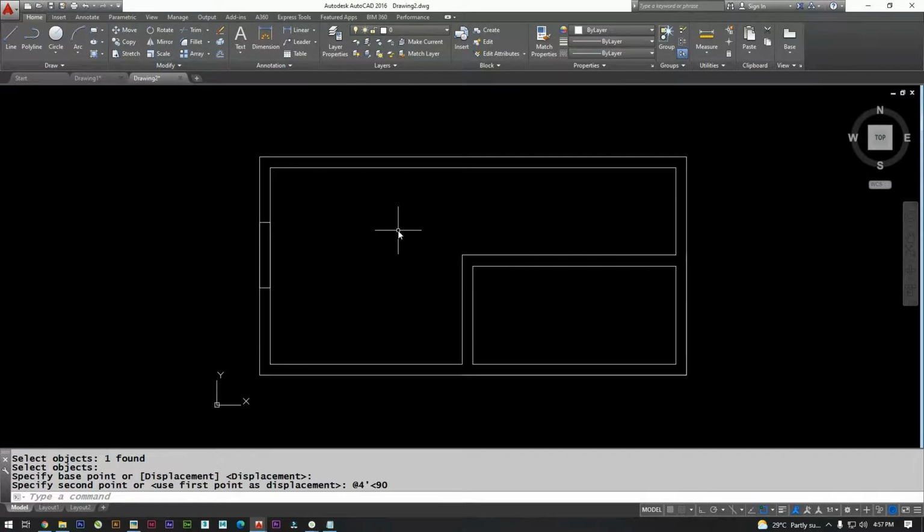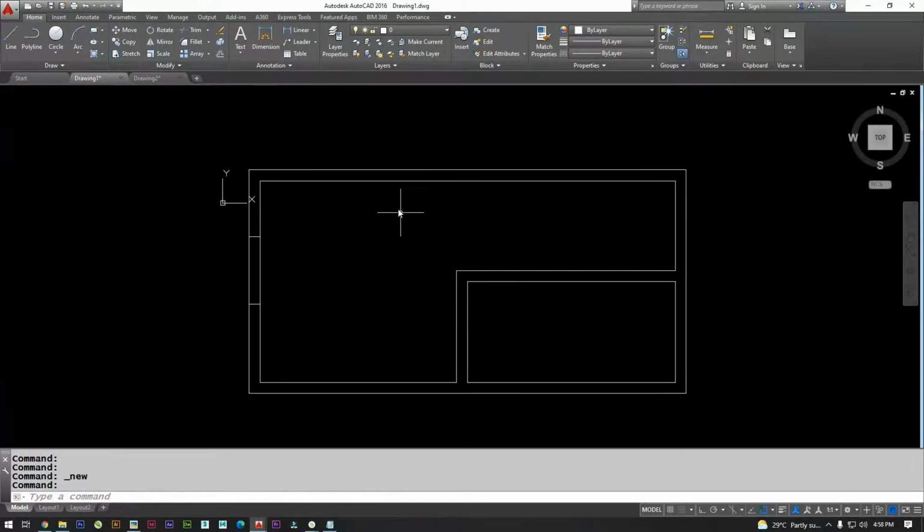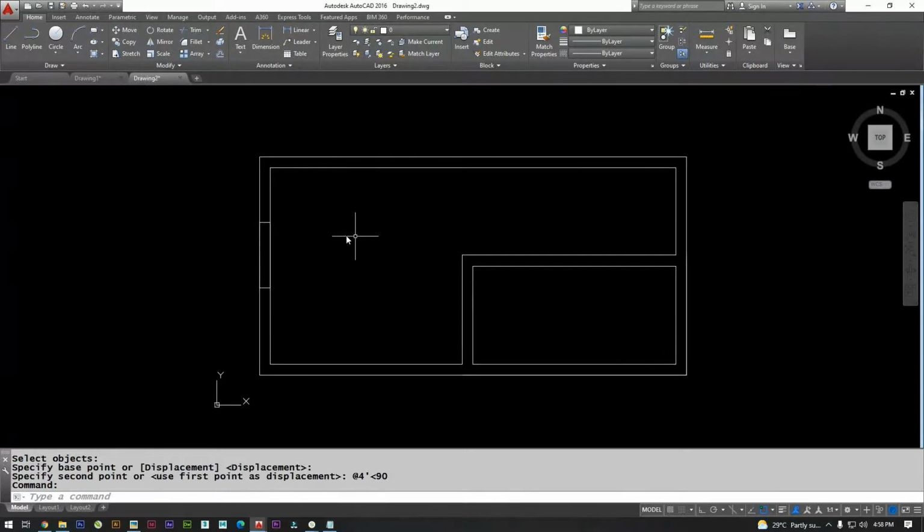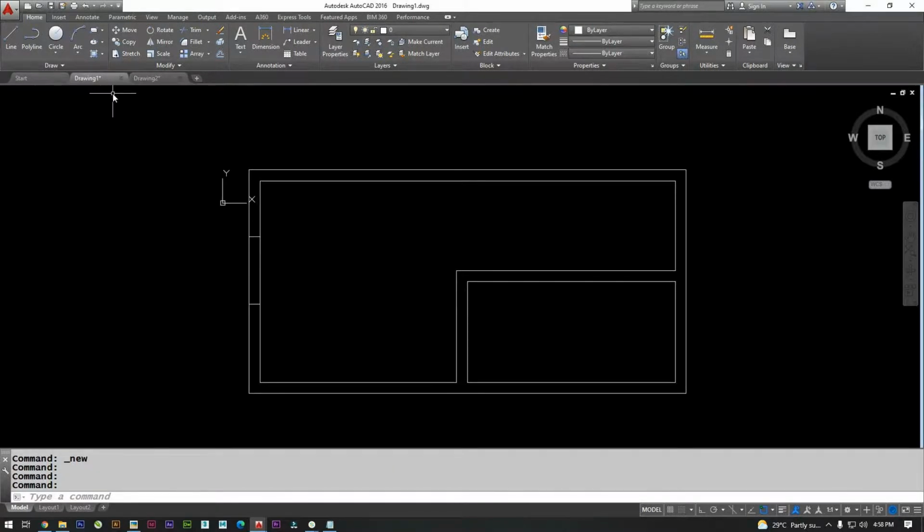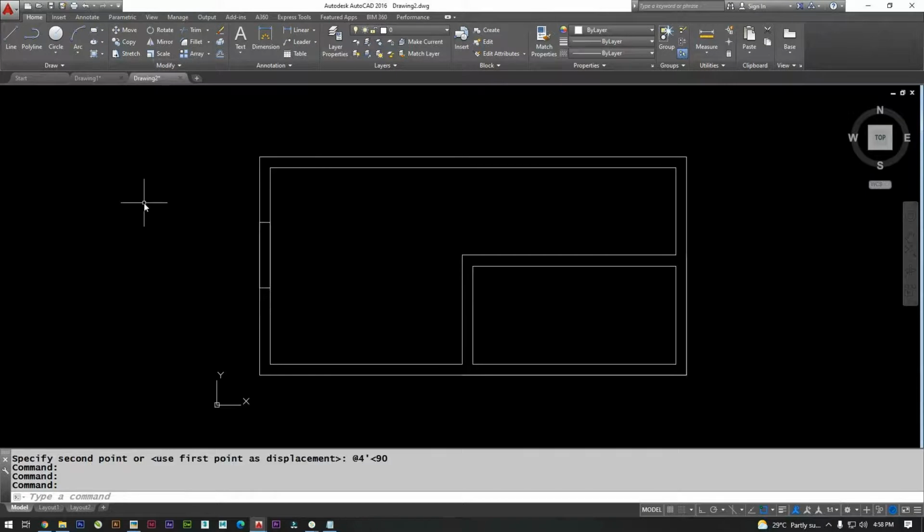Same drawing, even this is the same drawing. So either in units you can set it directly to architectural and give the value without any conversions, or if you are flexible with the conversion you can just do it with a line by keeping decimal in the units. So come to a conclusion after practicing both the ways. Don't conclude this method is easy or this method is difficult. First practice both the ways, then decide which method is easy and start following that.